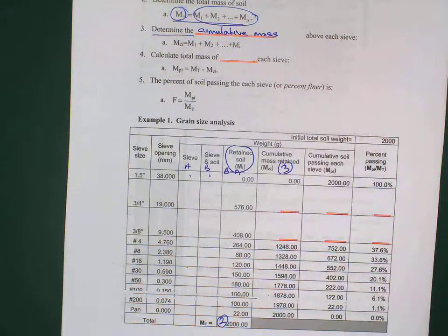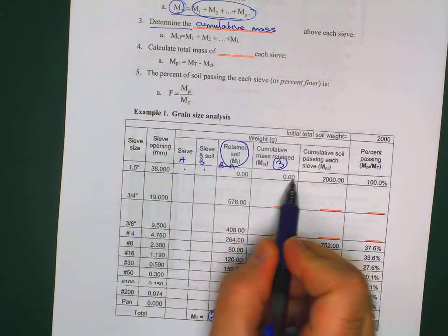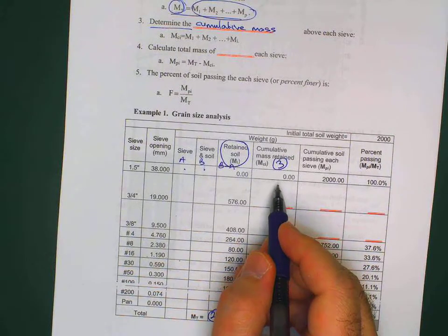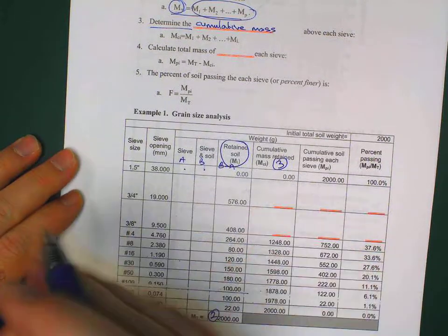You have to put that larger sieve on the top, make sure that it passes. Because if you don't do that, you wouldn't know whether the size would be that size or maybe there's a larger size there that you missed. Okay? So the very first number should be 0. Is this clear? Okay. So the very first sieve is 0. The size needs to be larger than the largest that you have in your soil.